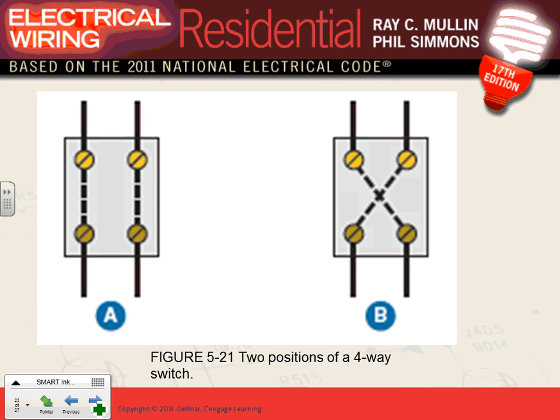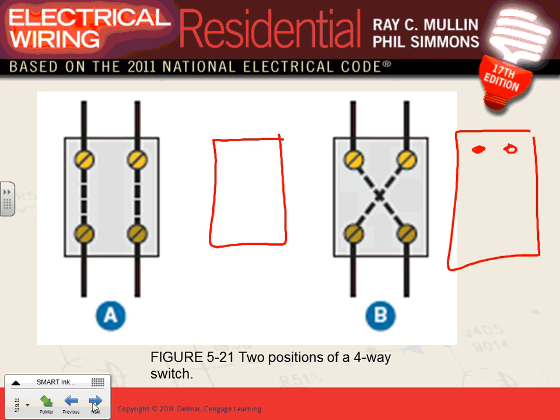If you have a 4-way switch, guys, 4-way switches typically go with 3-way switches. So I'm going to put two terminals here and a couple of terminals here. Everybody knows what the 3-way switch is? Two 3-way switches will give you switching from 2 locations. If you need a third location, you have to add a cross switch like this, or a 4-way switch. If you need to switch from 100 locations, two of them have to be 3-way switches. That will give you 98. So that will be 2 3-way switches like this, and the rest of them have to be 4-way switches, right? Do you know that the 2 at the end always have to be 3-way switches? The one in the middle, or the ones in the middle, can be the 4-way switches.